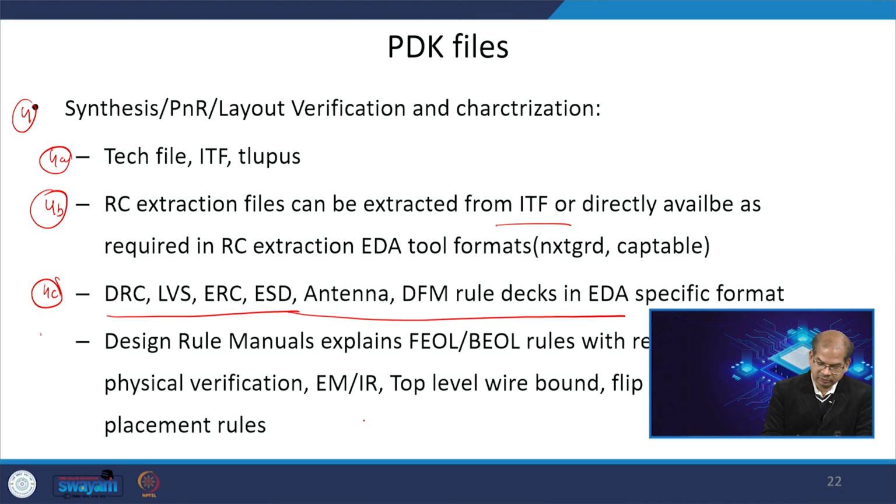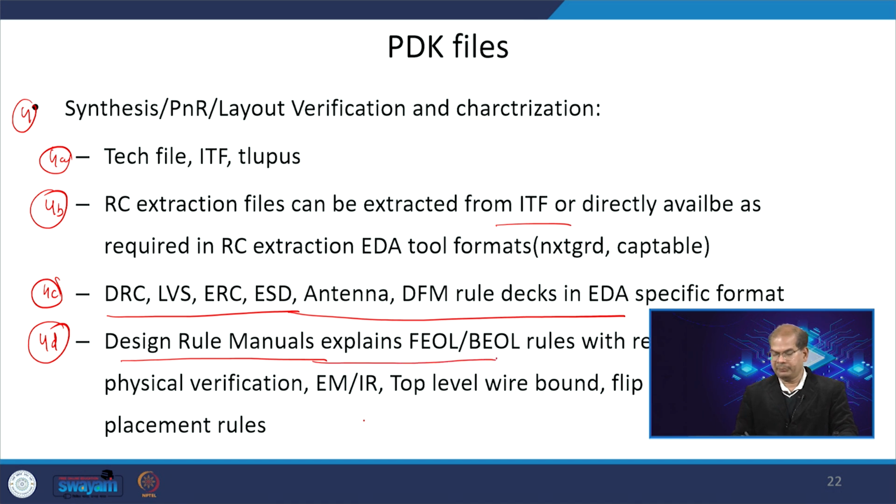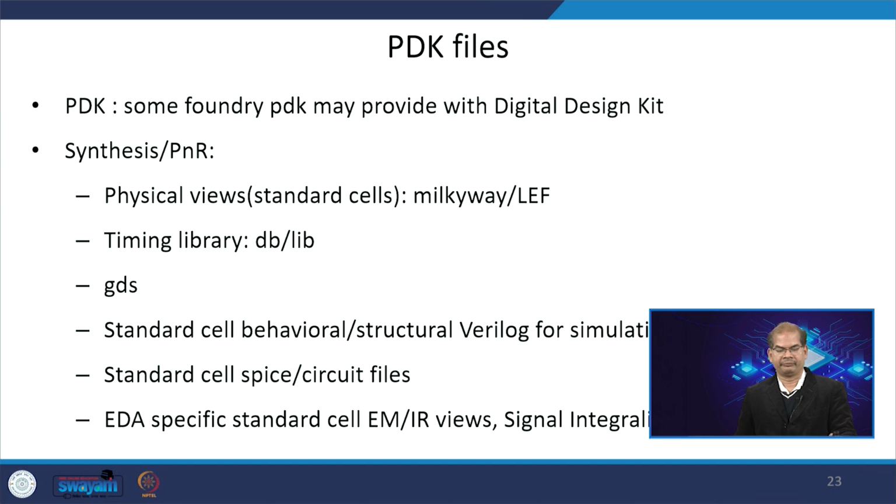It also has design rule manuals which explain the FEOL and BEOL rules with respect to the physical verification. It has EM electromigration, IR drop related files, top level wire bond, flip chip pad and placement rules, all these are also provided with the PDK.